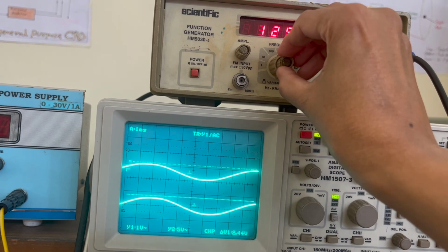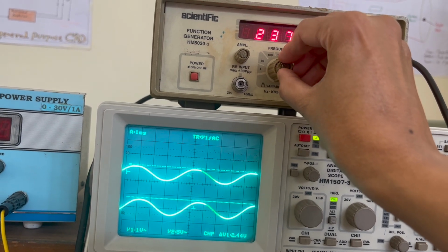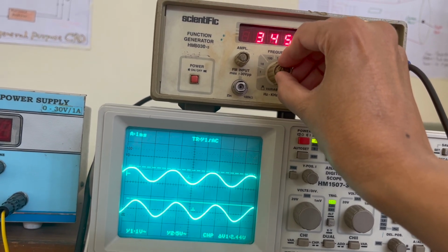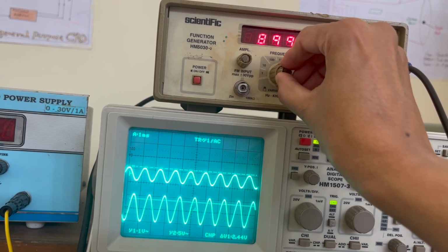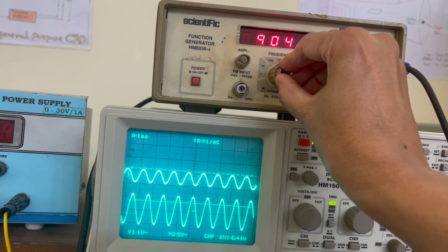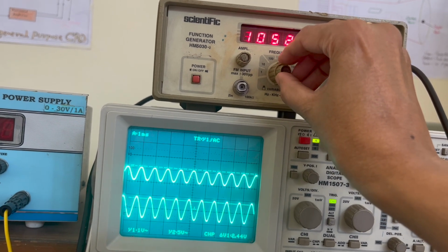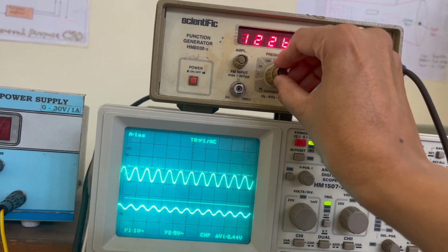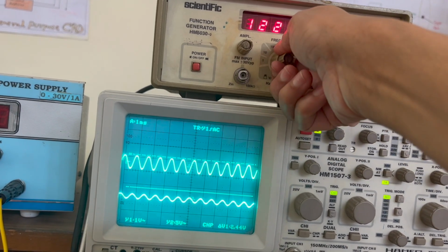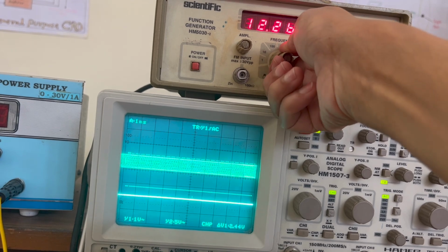This is the Chebyshev fourth order filter, which is a low pass filter. And there is one more thing, we have ripples in the pass band. So, see, the amplitude increases and then decreases. So, this is a ripple. If it is a fourth order filter, we will get two ripples in the pass band. So, let us observe it.